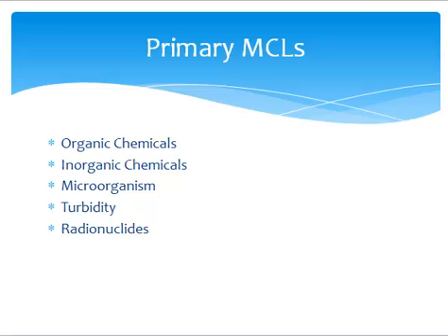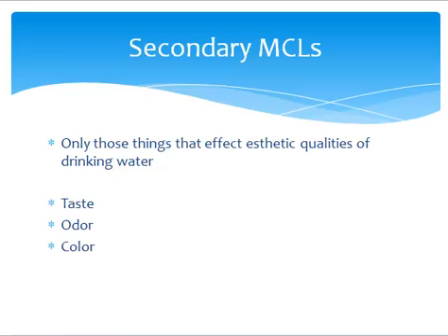The concept of overflow is that suspended particles that settle at a velocity faster than the overflow rate will settle to become sludge. Here is the formula to calculate overflow rate. If you are given an overflow rate of 700 gallons per day per square foot, determine the minimum settling velocity of suspended particles needed to remove them from a settling tank. Notice that particles that settle faster than this will become sludge at the bottom of the tank.